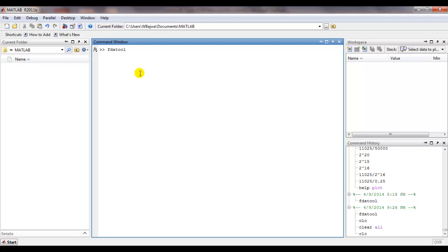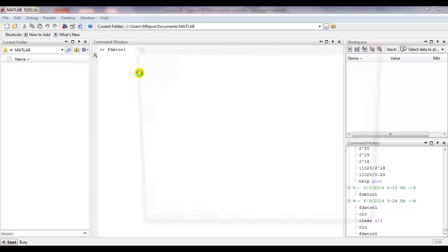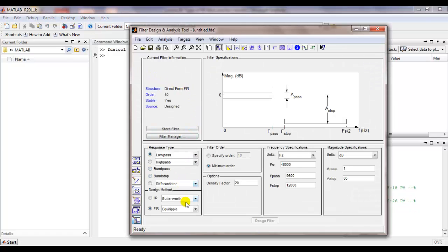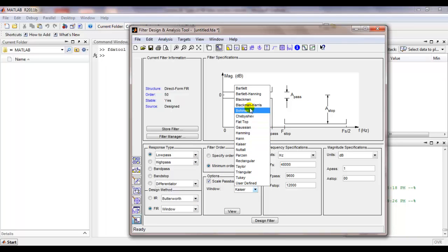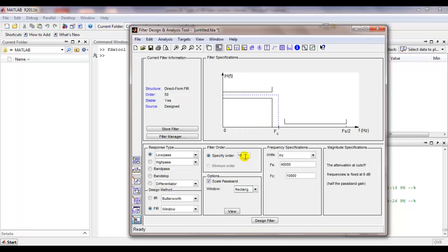So in MATLAB, there is a filter design tool called FDA tool, and we won't fully learn its functionality right now. I just want to use this tool to see the placement of zeros and how that affects the response of my filter. So I'm going to launch this, and I'll be making some changes which may not fully register with you right now, so you can ignore that for the time being. The key idea is that MATLAB is asking what the value of capital M is, the order, which is the degree of the polynomial you are working with, or how many zeros you are going to have. So I'll just say it is 4.